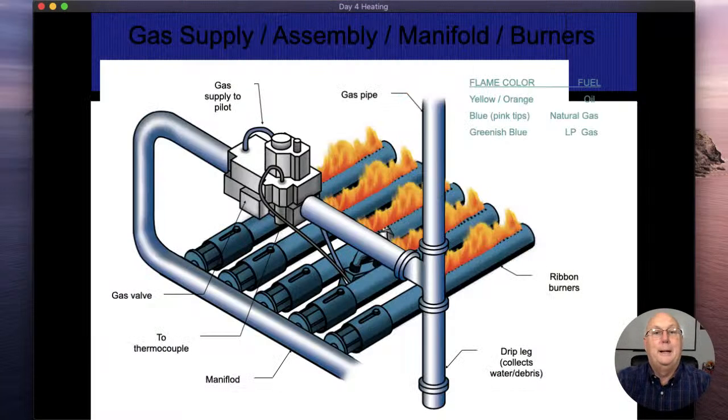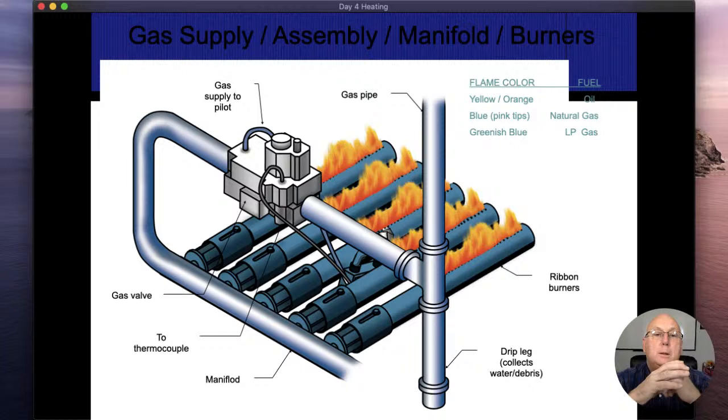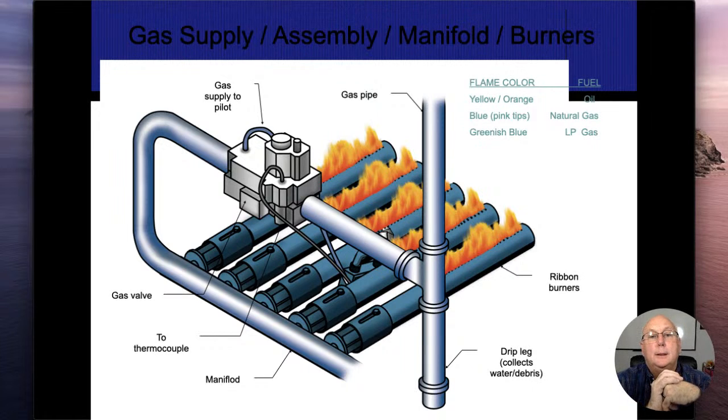All right, a little bit on the burners. I'm not going to go real heavy. Typical manifold burners on here. Those orifices that I was talking about are going to be at the bottom. My device actually went dead, so I can't put a cursor on there. Where the manifold comes in there's going to be a small pinhole. That's the orifice. If I change this from gas to propane, that orifice has to be changed out as well. Larger opening for gas, smaller opening for propane.